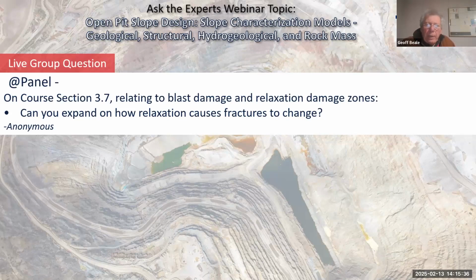And so if you have, let's say, 20 or 30 meters of continuous head in a fracture that is, let's say, 20 or 30 meters behind the slope, that's a significant proportion of the stress field. And a lot of the instability we're starting to think can occur because of the driving force of the water in fractures that are subparallel to the slope.